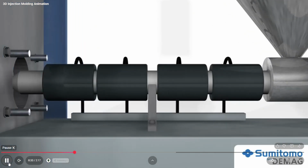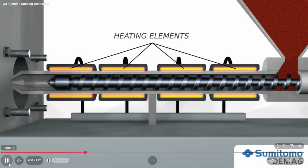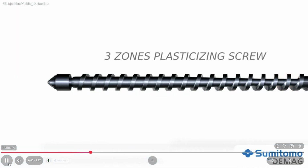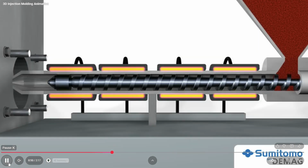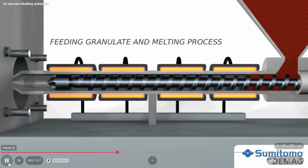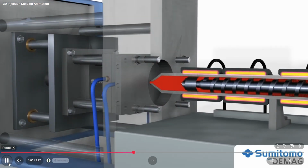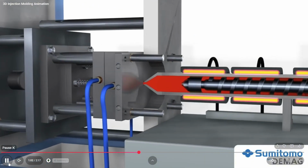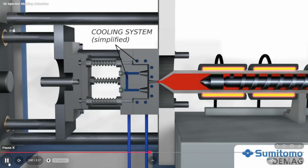But the difference between injection molding and extrusion is that the screw moves axially, so it would act like a plunger. When the material melts and fills the barrel, the screw will shoot the material into the mold. So it moves from right to left to push the material into the mold. And the mold has a cavity in it based on what shape we want to form.